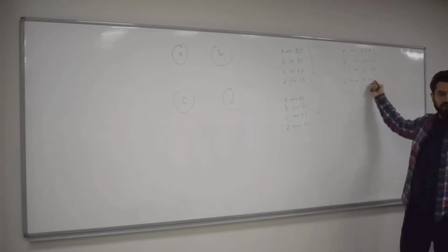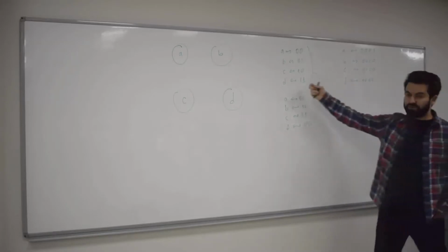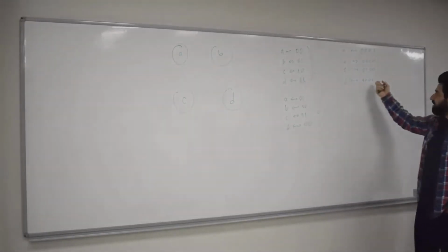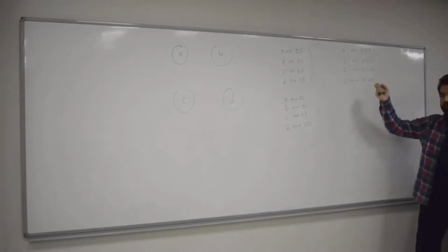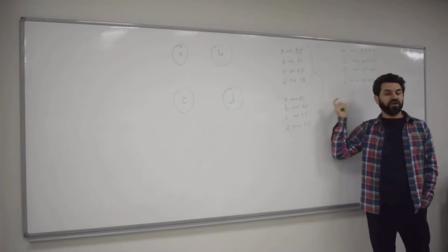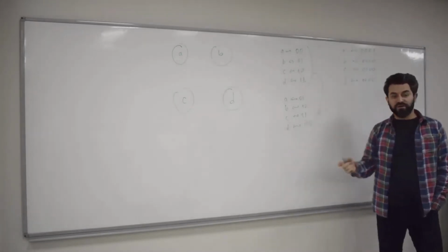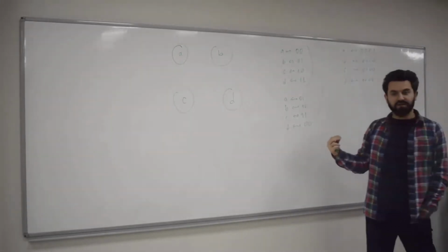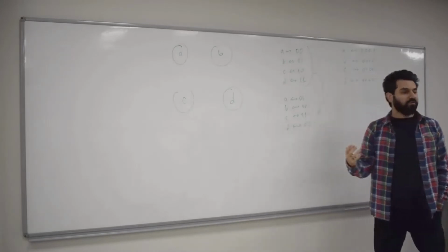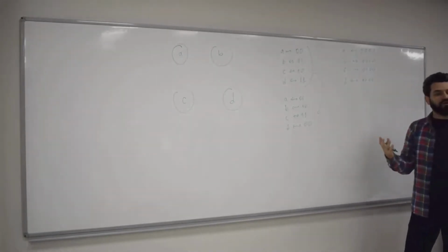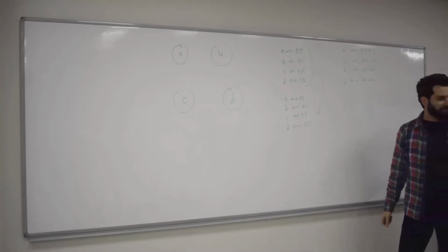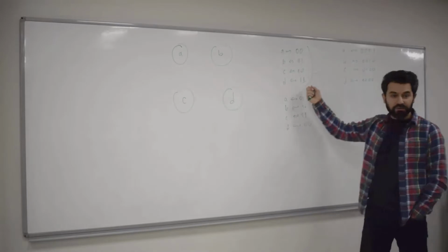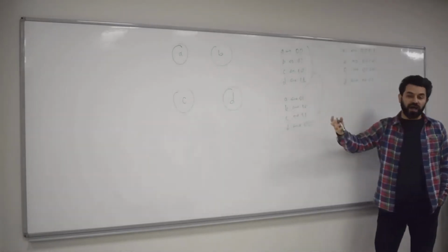However, you're using 4 flip-flops here and 2 flip-flops here. Most of the time, you use less combinational logic here and more combinational logic here. There's a trade-off actually between them. You can design the same exact circuit. So this state assignment problem is not so straightforward. That's what I'm trying to give you as a bottom line message today. This state assignment problem is not a straightforward task.